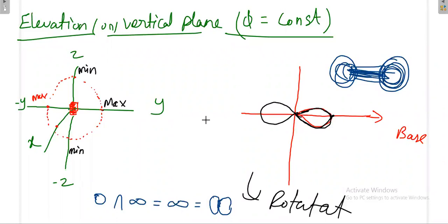There is another way also to get this shape. If you have a spherical balloon, somebody may try to connect this end with this end internally. Then imagine what will happen. The balloon will go like this. Once you bring this side here and this side here internally, that is also similar to the tumble shape. This balloon structure is the actual 3D radiation pattern of the Hertzian dipole antenna.